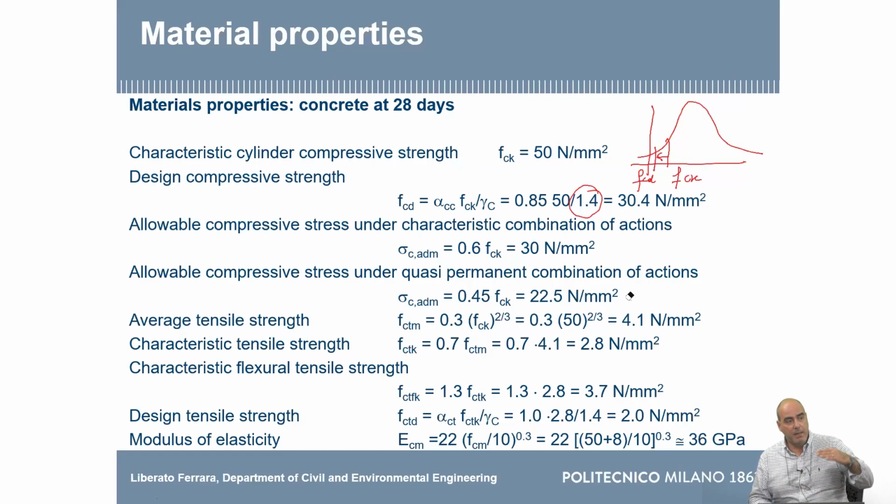So keeping the stress below this limit helps you in controlling the creep. You cannot avoid creep, but you can control it. If you keep the stress low, your creep will grow lower. What if it's higher? Well, if it's higher, you must abandon this approach.